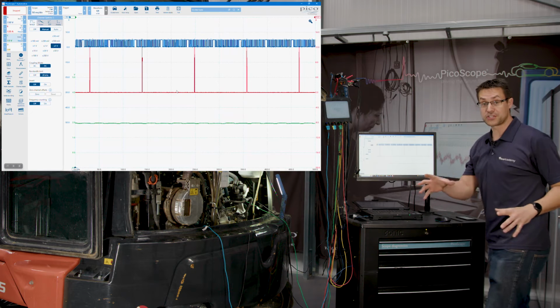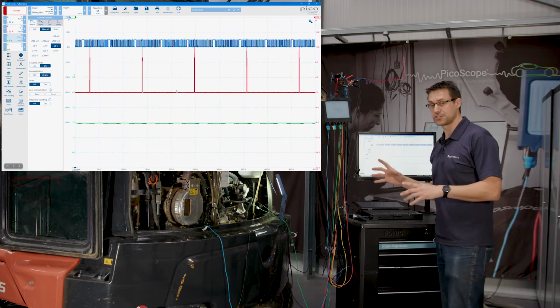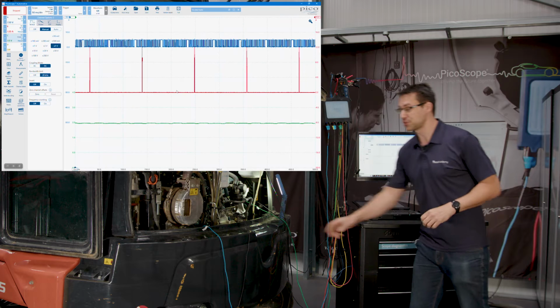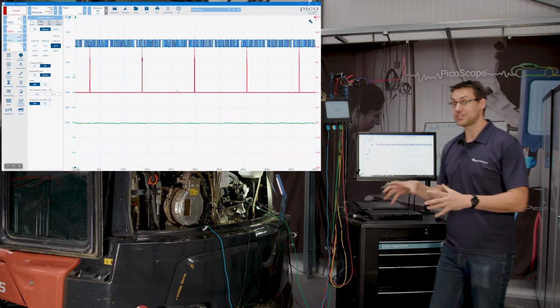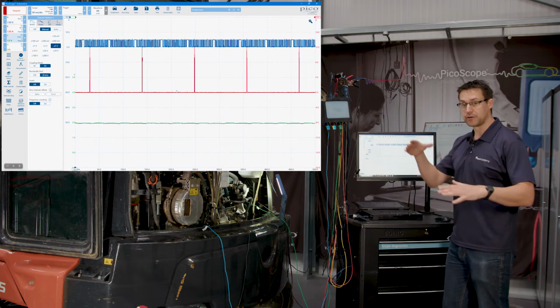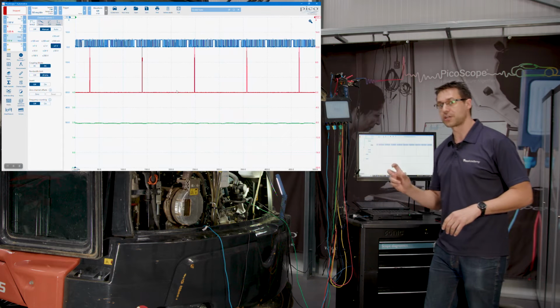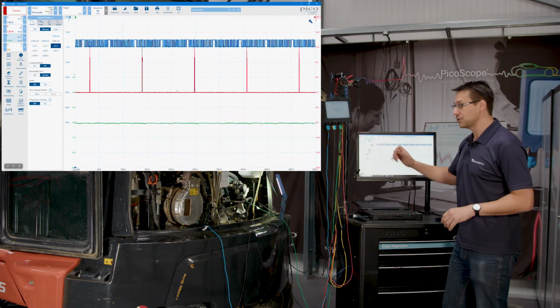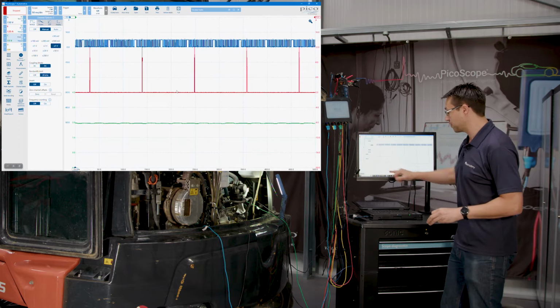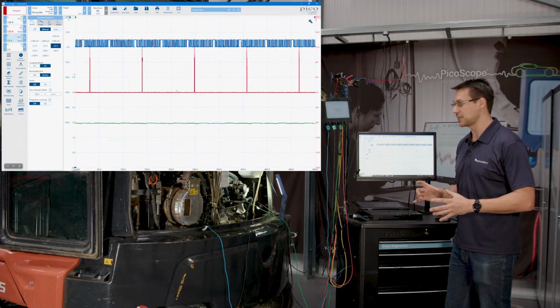Okay, so hopefully you could see the big change between the two signals when I had it connected to the chassis ground and then to the sensor ground. So bandwidth limit helps get rid of quite a lot of the interference from the injector spikes, those frequencies that are occurring. But using the sensor ground removes a lot more of that interference that we were seeing as well.